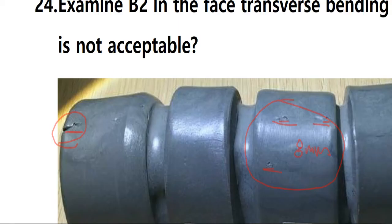Measure this one, over 6 millimeter, then reject. And if you see in the question slag inclusion or fusion type discontinuity, then the criteria becomes 3 millimeter.